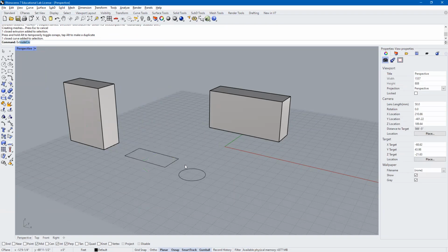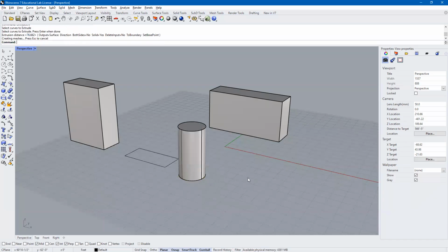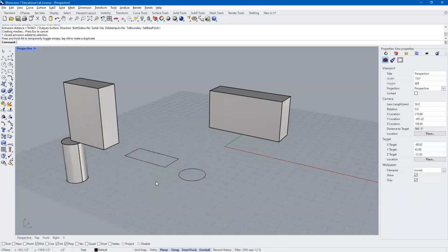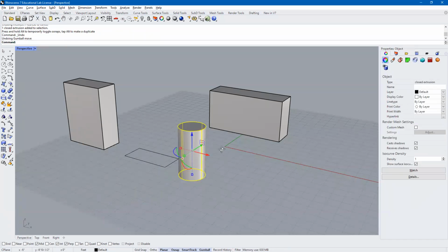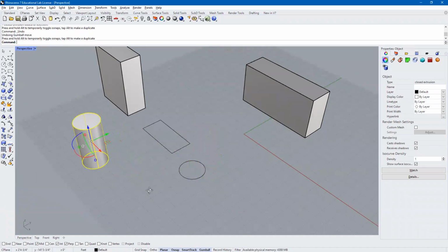It's using it as a template to then generate the shape. So don't forget that. And then the other thing here, when you do an extrude curve, please understand that in Rhino, this rectangle and this circle, they are referred to as curves, or they're recognized as curves. So I can click on that, enter, and generate my extrusion from it. And then I'll move this out of the way like that. So, and I moved it, I grabbed it from the wrong direction. Let me do this again. 1 second, because I want to move it. There we go. From this XY plane like that.